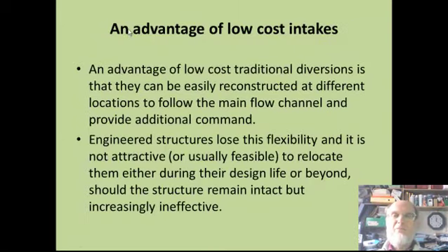Now, it's worth emphasizing the advantage of low-cost intakes is that they can be easily reconstructed at different locations to follow either the main wadi flow channel or to provide additional command. Engineered structures lose this flexibility because it is not attractive or feasible to relocate them during their design life or beyond. So the structure tends to remain intact but is increasingly ineffective.